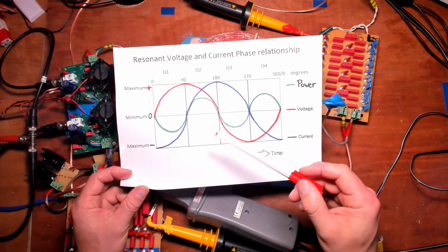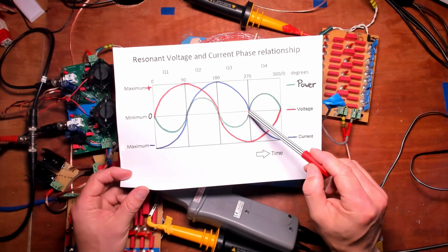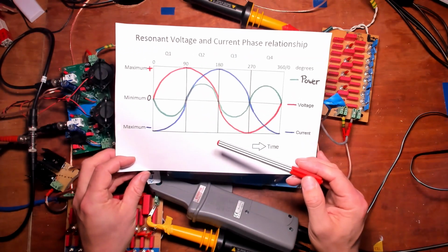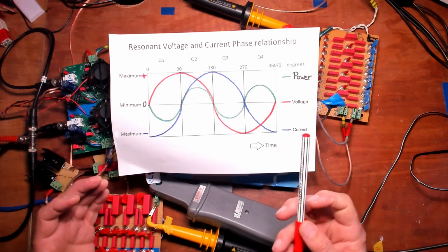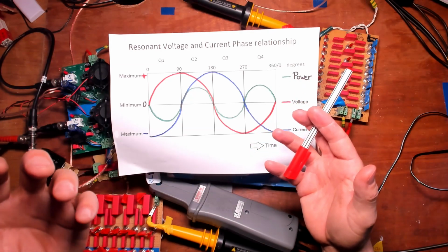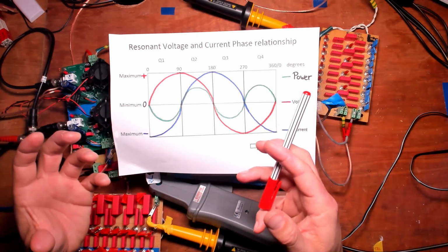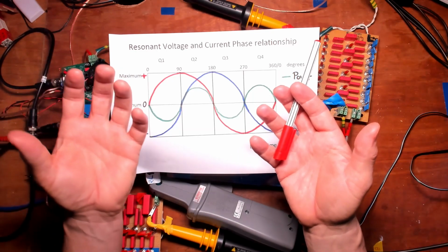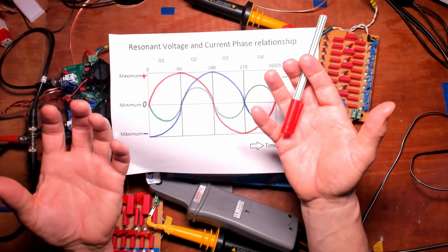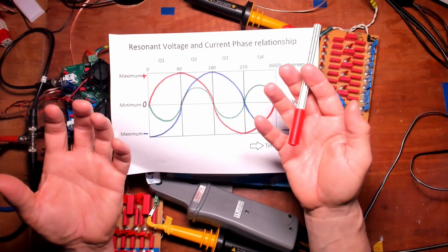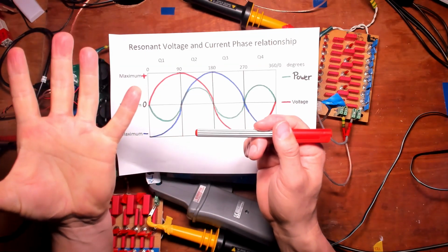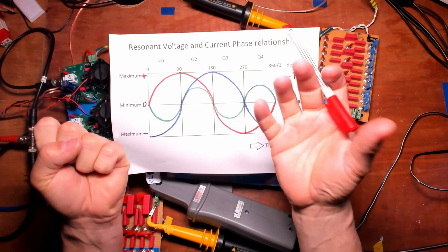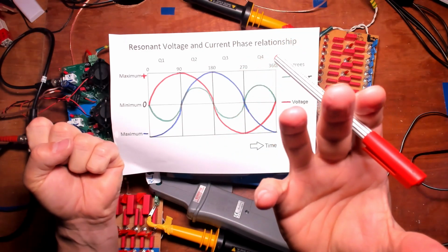To explain a little bit more about the generation of power, which is negative, or the consumption of power, which is positive, we need to understand that the electric energy of the series resonant system of the L2 coil and the L2 capacitor is exchanging energy between the capacitor and the coil. And I'm measuring the current between the capacitor and the coil. So when the coil is generating negative power, then the capacitor is being charged up. And when the capacitor is being discharged, then the coil is being charged up. It is consuming power, so then we have a positive cycle.